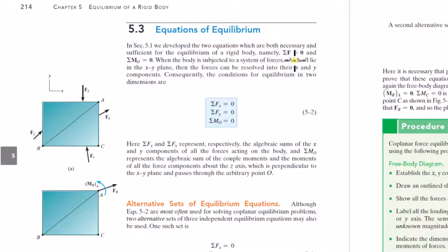So all we were doing in chapter 3 was that since all the forces met at a point, you could make a free body diagram just as a particle, as a point in space. You bring all the forces to that point and sum the forces about that point. And it was equilibrium, so they had to be zero. That's what we were doing. Okay, but if you break this down into components in the Cartesian direction, then you can do this on an axis by axis basis. You can sum the forces in the x, they have to be equal to zero.